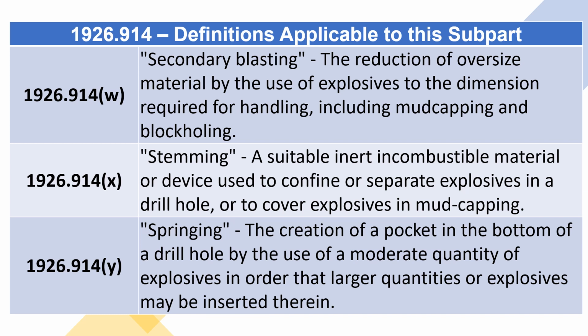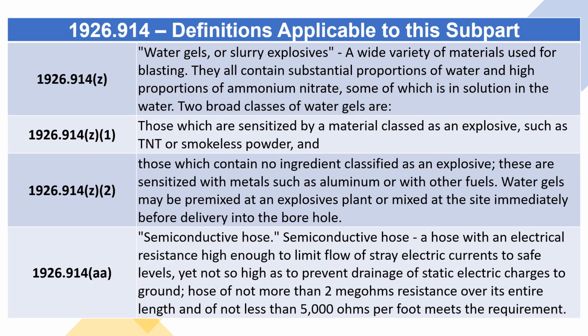1926.914(y). Springing. The creation of a pocket in the bottom of a drill hole by the use of a moderate quantity of explosives in order that larger quantities of explosives may be inserted therein. 1926.914(z). Water gels, or slurry explosives. A wide variety of materials used for blasting. They all contain substantial proportions of water and high proportions of ammonium nitrate, some of which is in solution in the water. Two broad classes of water gels are